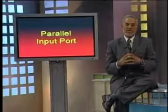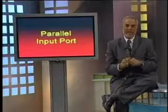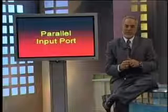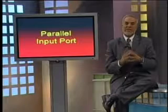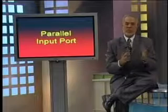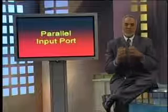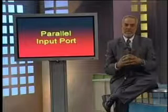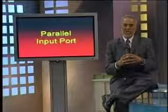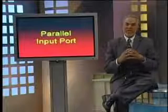We say that the CPU, the Falcon processor, would read the status of the 16 switches using address 7E. Some of the switches might be on, others might be off. After reading the status, it would pass on exactly the same status without any change, utilizing an output address which is DE.